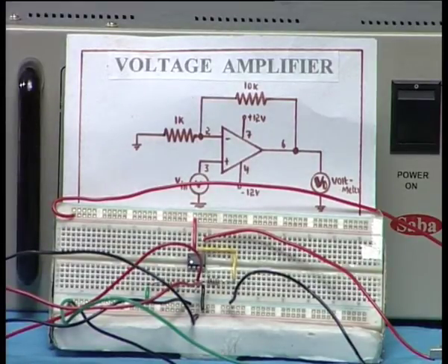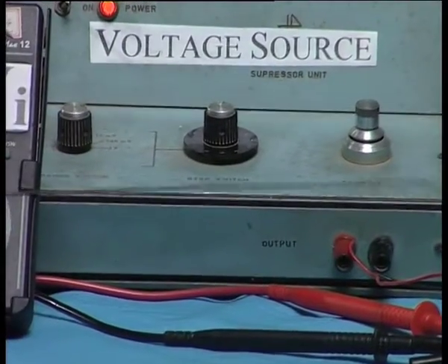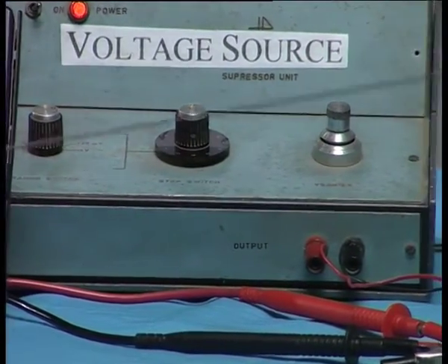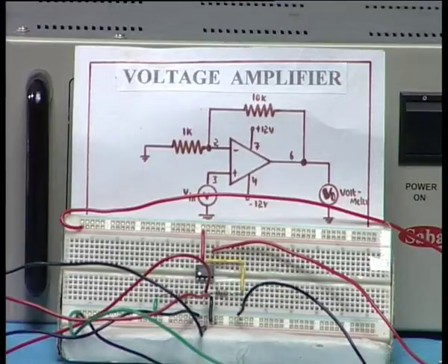You can see what I have done is now with reference to DC, because the operational amplifier can amplify starting from DC. The bandwidth starts from 0 frequency up to 1 megahertz, for example, when you have unity gain. But when you have a gain of 11, automatically the bandwidth will be reduced because the product of bandwidth and gain should be a constant.